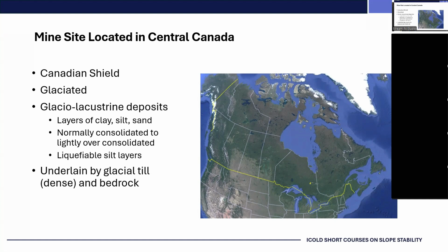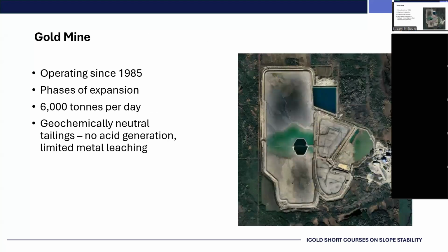Earlier in Paul's presentation, when he was introducing the flow chart, he talked about if you can avoid contractive layers in the dam fill or foundation, you should do so. We have proceeded with centerline construction on these dams, so we have taken the contractive elements out of the structural portion of the dam fill, but we had to contend with the contractive layers in the foundation.